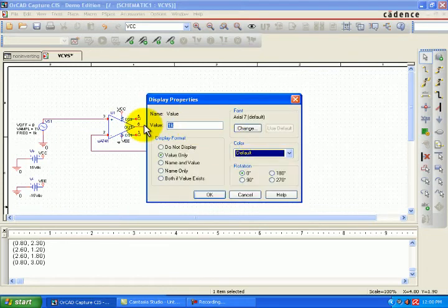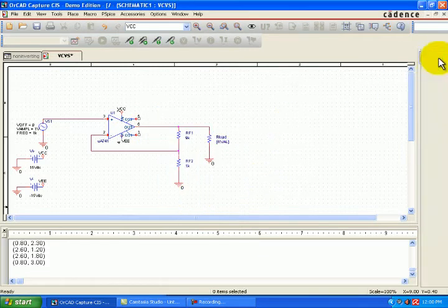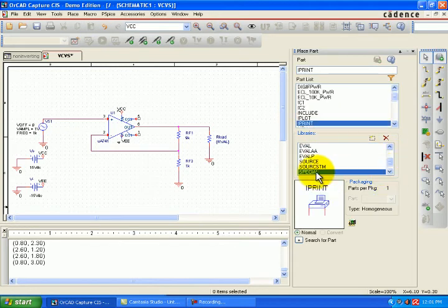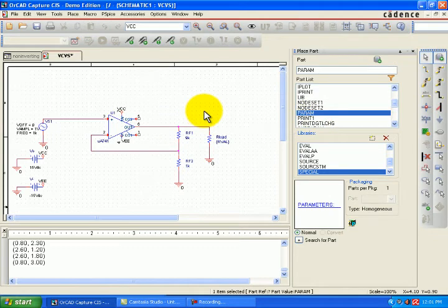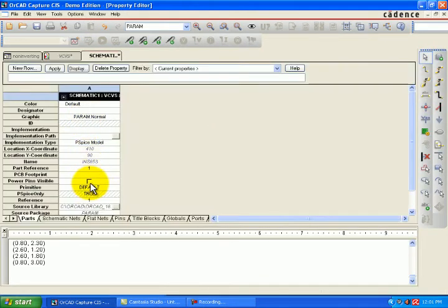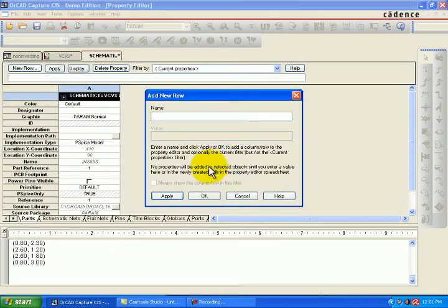This one is the load resistance. Change the value of resistance, RVL, with a different value of the load resistance we're going to give. This will be like varying load or a parametric sweep. Configuring the input signal as 1 volt amplitude, 1K frequency. RVL equals 1K. Select 1K for RVL. So this is the parameter which is going to be changing.